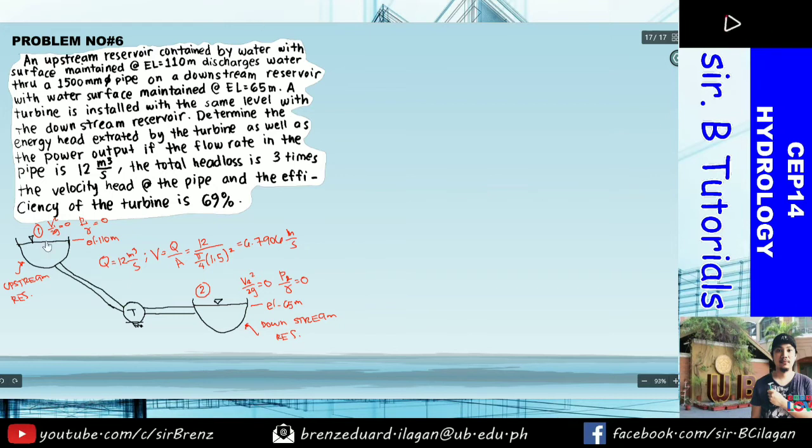Okay, so apply na tayo ng Bernoulli's energy equation. Again, ang sabi ko nga, maximize nyo kung saan points maraming ma-eliminate. So ang gagawin natin, apply BEE from point 1 to point 2, so from this point up to this point. That will be the total energy at point 1 plus or minus the summation of the head loss from point 1 to point 2.